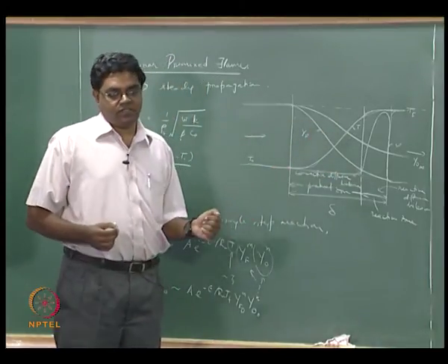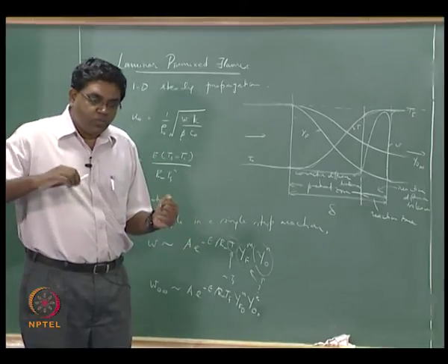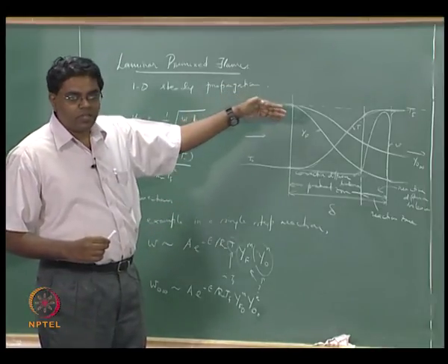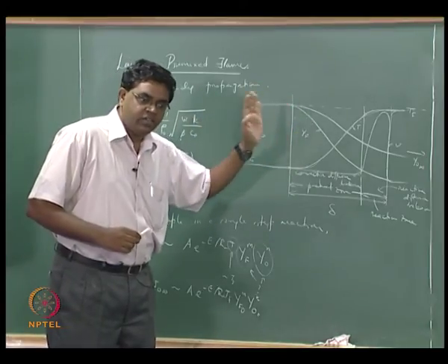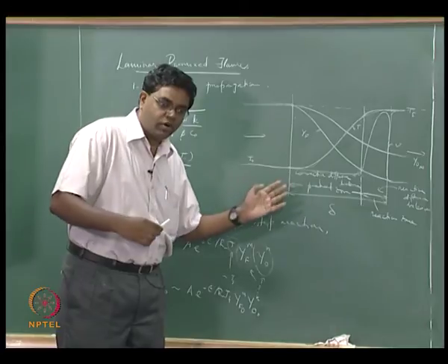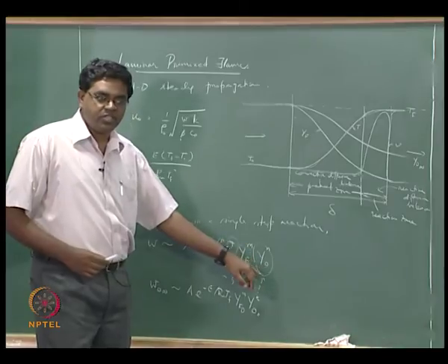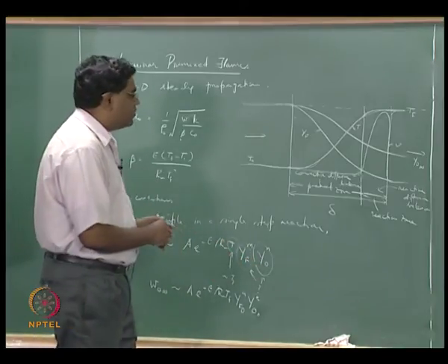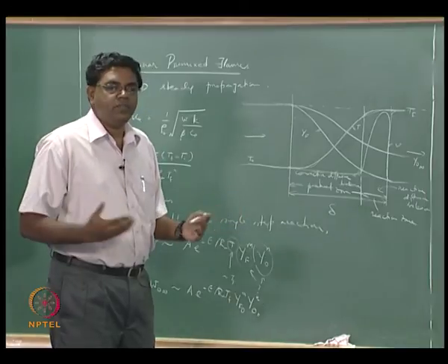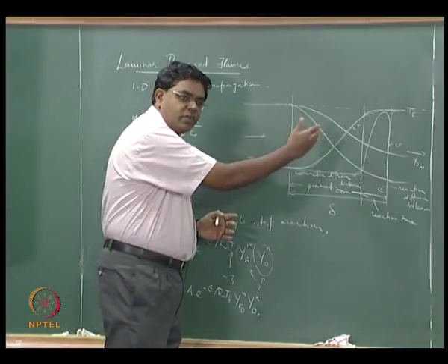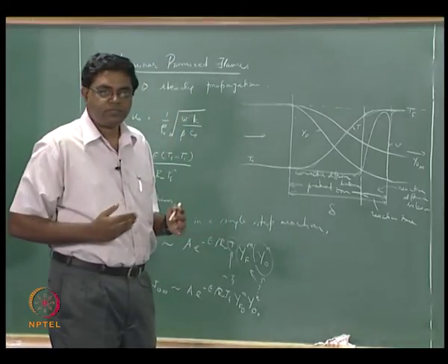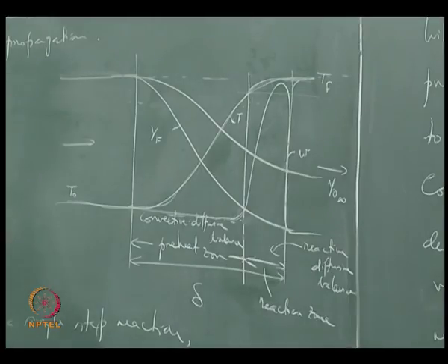That need not be the case, and that is why we are talking specifically about the reactant Lewis number and abandoning the product Lewis number that we originally constructed our argument on. The reactant concentrations are the ones showing up in the law of mass action, and that's what we are beginning to correct. We want to see if the reactant Lewis number is not 1, is it going to be this way or that way, is this profile going to actually change? So how do you take this into account?